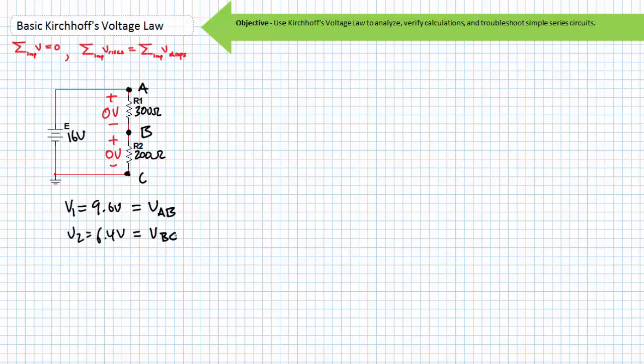Now, pause to consider the voltage at node A with reference to node A, the voltage at node B with reference to node B, and the voltage at node C with reference to C. This may sound stupid because voltage is a two-point measurement, and obviously all three of these, in effect, single-point voltage measurements should be 0 volts. True, this is what you'd expect. However, all bets are off because our observations aren't matching our expectations, and there is an open somewhere in our circuit.